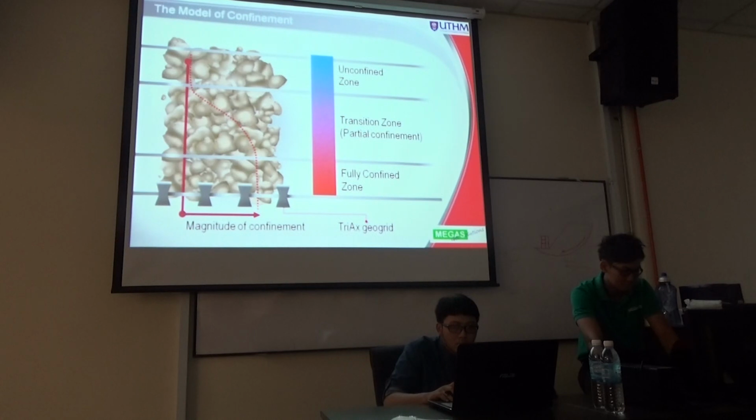If, for example, we design for a haul access road or heavy duty pavement, we probably need to use multiple layers because the thickness that we need is much greater, for example 600 mm or 800 mm, depending on the load that we design for.